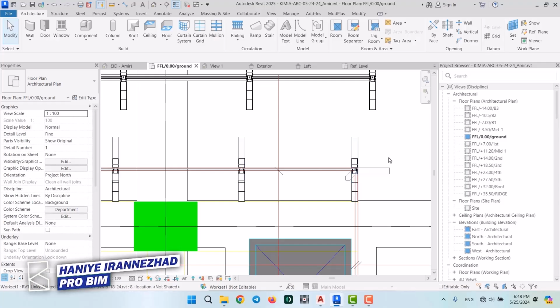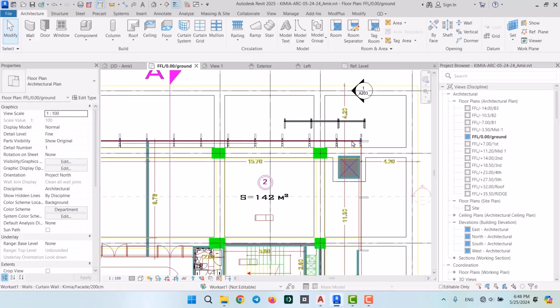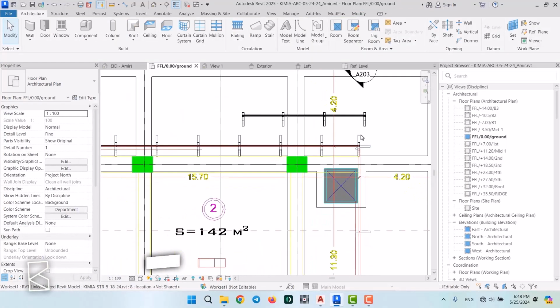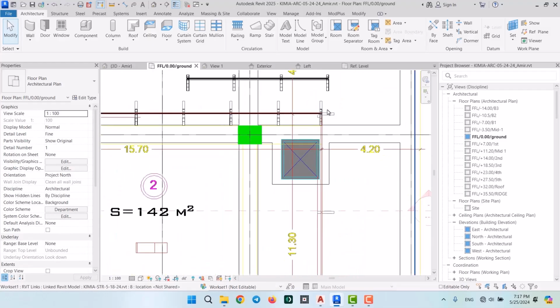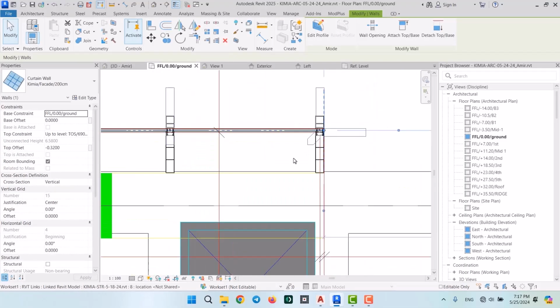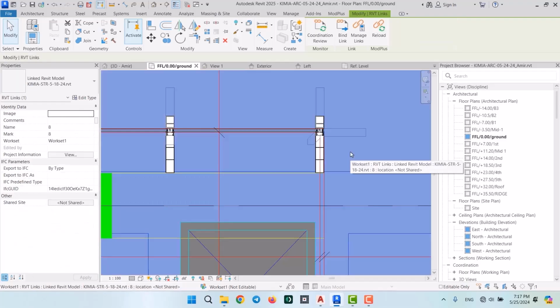These are the things that we're going to do in the next video, and then we will draw the rest of the curtain walls for the project. So now let's also try to add the mullions over here. You see what we have over here needs to be placed step by step and individually. And the reason for that is that you can't, for this type of mullion, assign certain mullion to one instance. This is something that you're going to have to do manually.